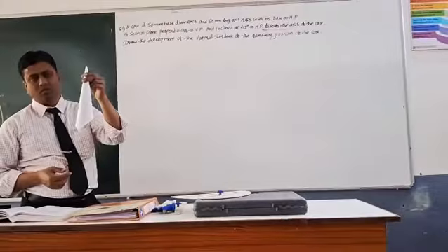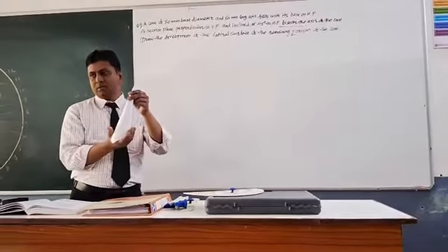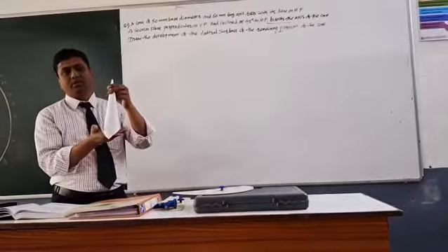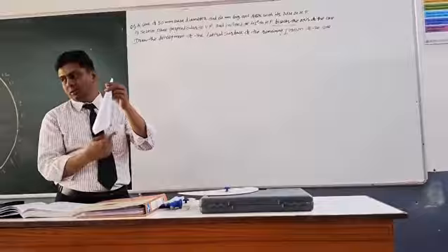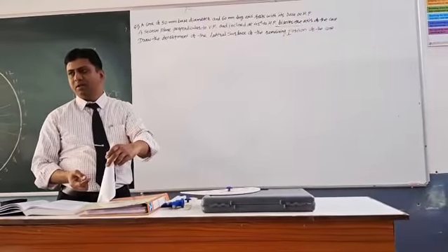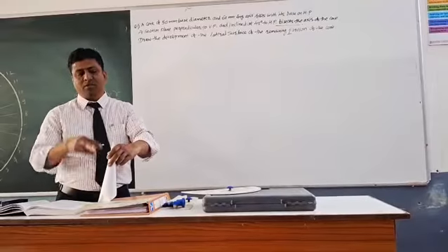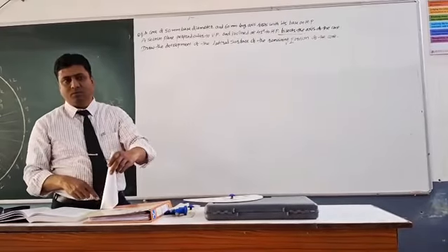Everyone knows the cone. Cone having one apex and one base. What is the shape of the base of the cone? Circle. When the cone is resting like this on the HP, when you see the cone from the top, you will get the top view. So what is the top view?